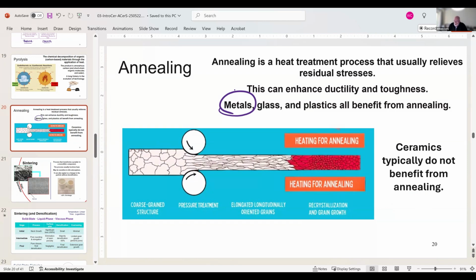Well, it was really easy to bend because it had been annealed. So they made the tube, and the process of making the tube elongates the grains. It also piles up dislocations in the system, and it becomes embrittled and very stiff. So they would anneal it, they heat it up, and it recrystallizes all that, heals all those dislocations. Now the system is pliable again.